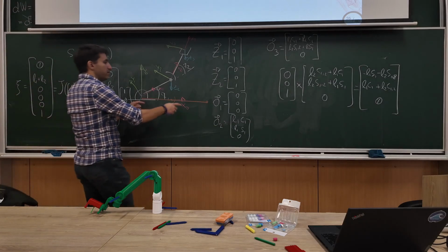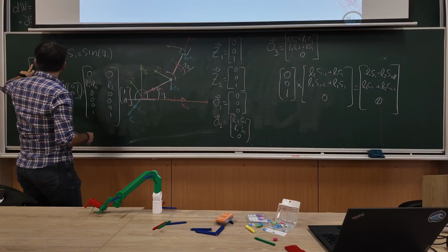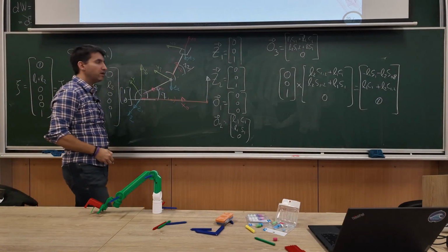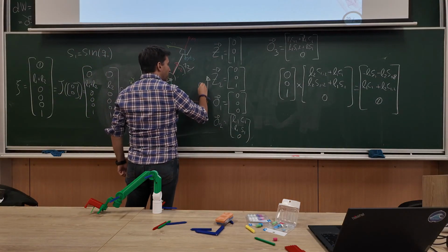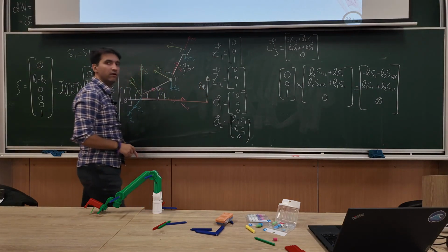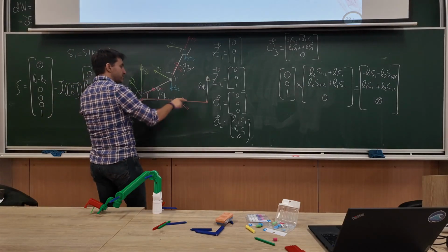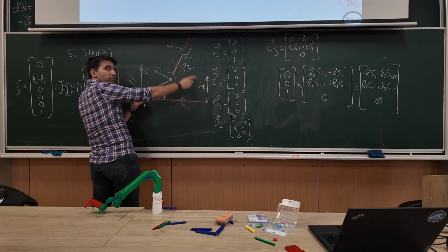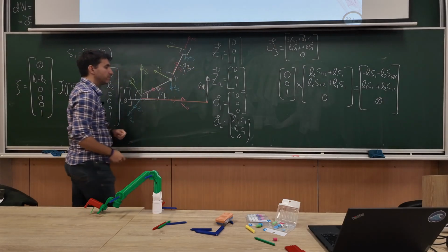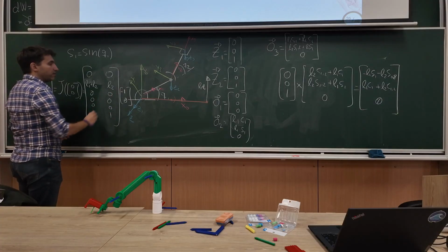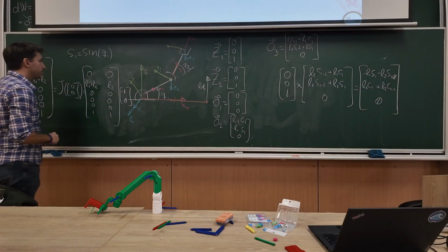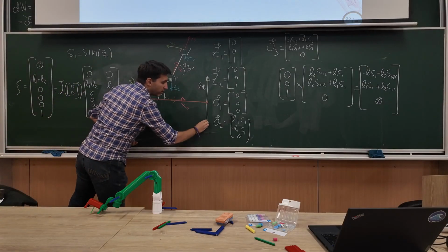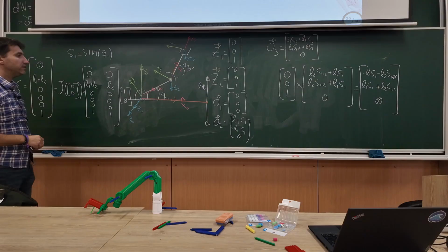So this tells me basically my linear velocity will be something like this, where the length of this is L1 plus L2, right? And it makes sense. If my robot is like this and I move this joint, instantaneously I will move upwards, and that will be my velocity. If I had here a minus, so basically rotating the other direction, I would have had a minus, and my vector would have been pointing downwards, right?